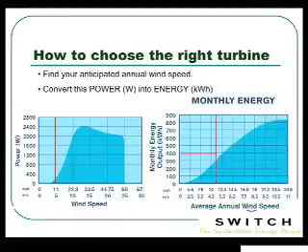So we'll use that same turbine, the SkyStream, as a case study. If you remember those wind roses that I showed you maybe 10 minutes ago, basically it was just under 5 miles an hour, or 5 meters a second winds in that area where I clicked. That was just around Kingston. So if you look at that, on average you can expect that you're down in this low end of your turbine. That's kind of startling. You think you're going to be out here.